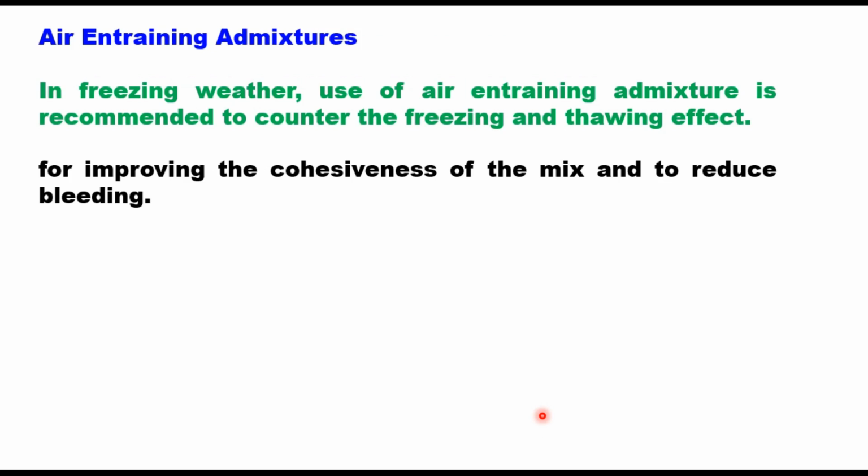The second is the air entraining admixture. In freezing weather, use of these admixtures is recommended to counter the freezing and thawing effect, and they are also used for improving the cohesiveness of the mix and to reduce the bleeding.